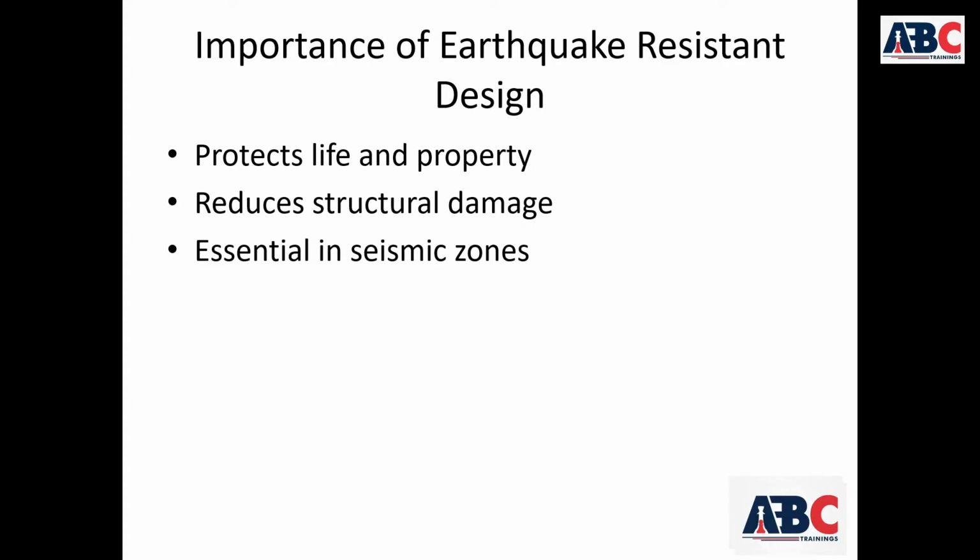Indian standards such as IS 1893 for seismic load calculation and IS 13920 for ductile detailing must be strictly followed. Ignoring seismic design in these zones increases the risk of collapse.